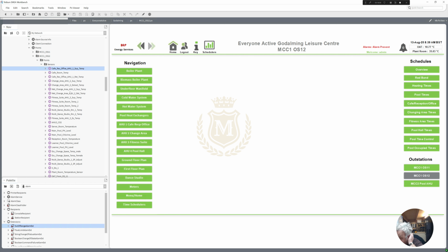Another thing I do, when you bring the BACnet inputs in, is I change the spaces to underscores, and any special characters I will change. So if someone's used a percent sign, I will actually put in the word percent, so that when I bring all the points in and I'm doing the histories to them, they don't look out of place with the special characters.